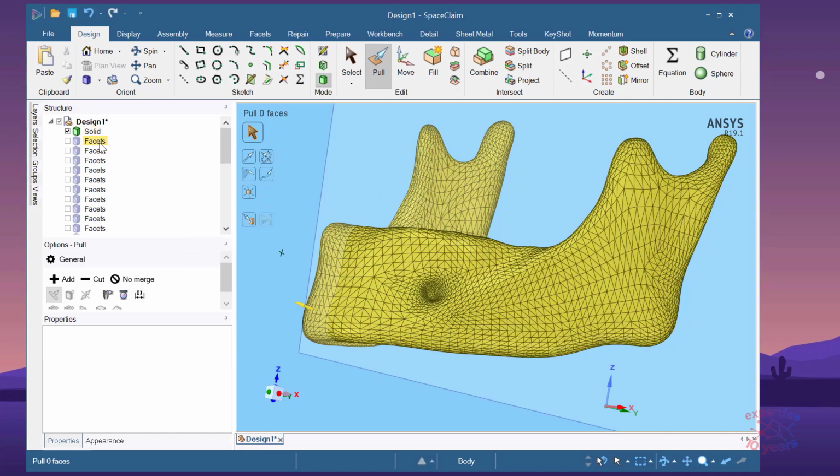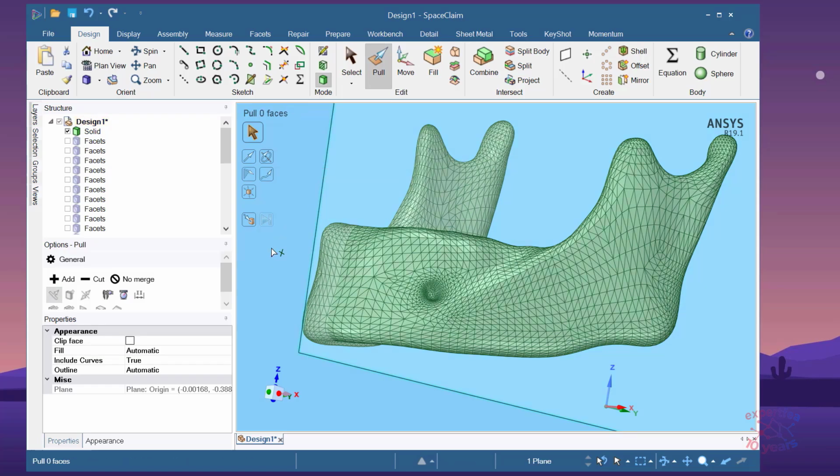You can now see that from the original, let's say, faceted body, which was hollow, now it is a solid. Maybe you ask yourself, how do we know it's a solid? Only because the icon changed? No. Let's go into section mode again: click the plane, then section mode.